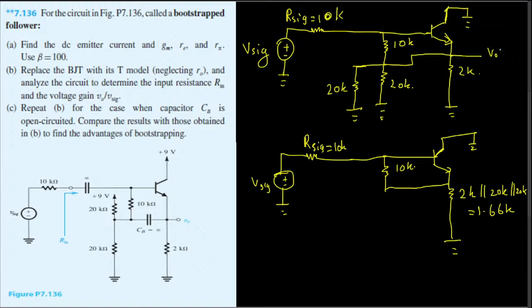Or if you want to try the shorter method, you can take two at a time. If you take two parallel resistances, the equivalent resistance is product over sum. So 20 times 20 over 20 plus 20. You find the equivalent resistance right here, and then you put that in parallel with this one. So this one times this, product over sum, this one times this over this one plus this. You find the equivalent and you will end up getting this. Okay, you can do it in two ways. Either way you will get this one.